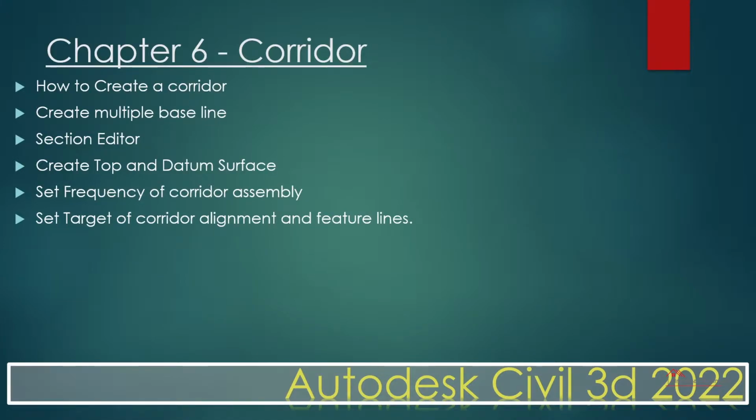So basically, a corridor model builds on and uses various AutoCAD Civil 3D objects and data, including sub-assemblies, assemblies, alignment, surface, and profile. The corridor manages the data, tying various assemblies to the baseline and their finished grade profile. A corridor can define and display components such as feature lines, which are defined in sub-assemblies, and surfaces using link codes and feature lines.